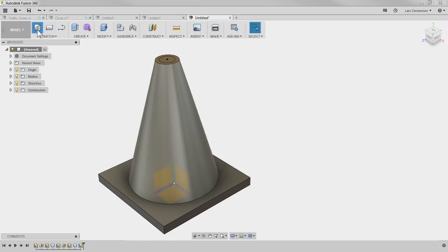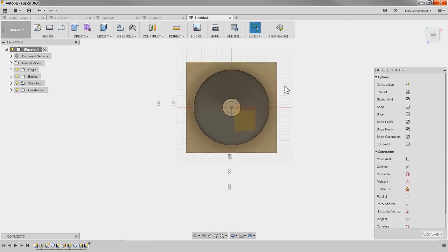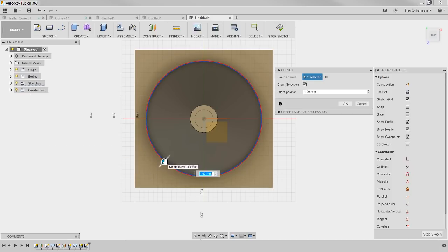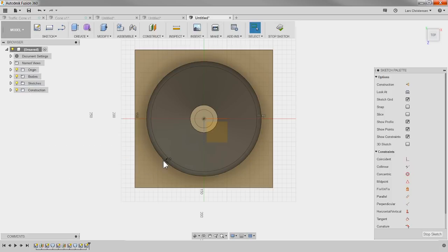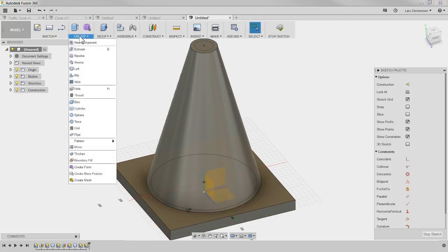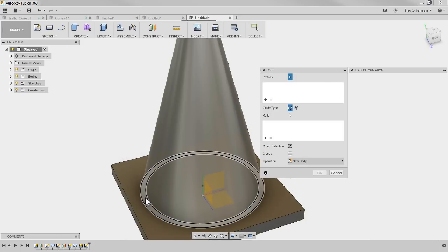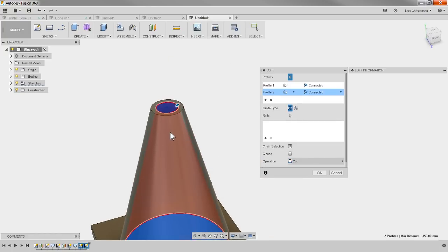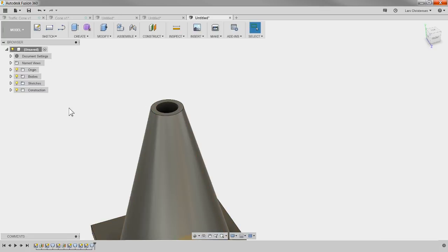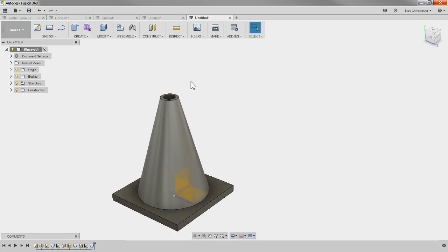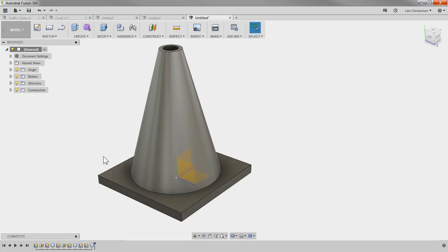And I will start another sketch down here, do the exact same thing and offset from this edge, -10. Now I have those two circles sitting in there. If I go back into the Loft command and select those inner circles, it's hard to see, but it turns red, meaning it becomes a cut, and we now have the same as we had before with the two other options.